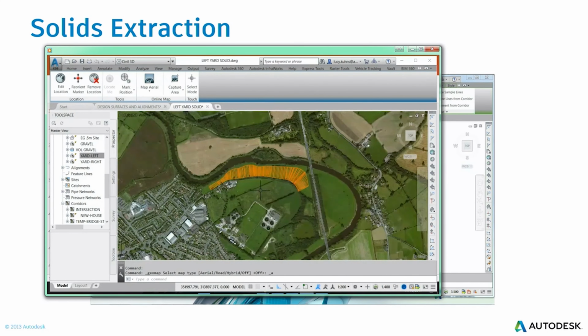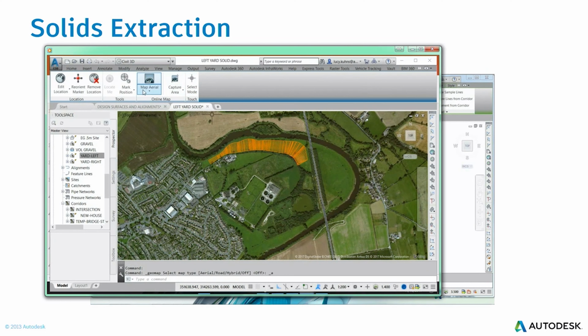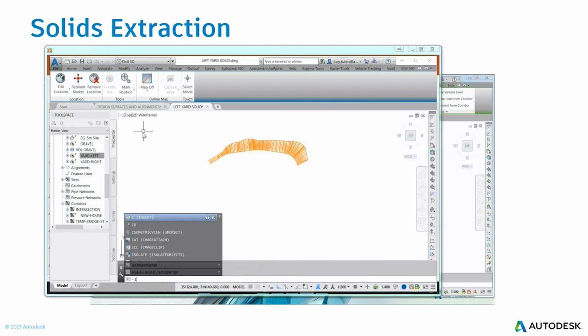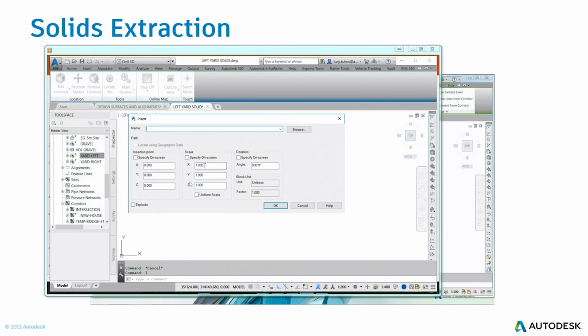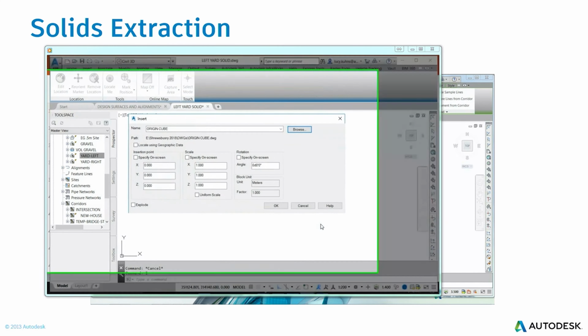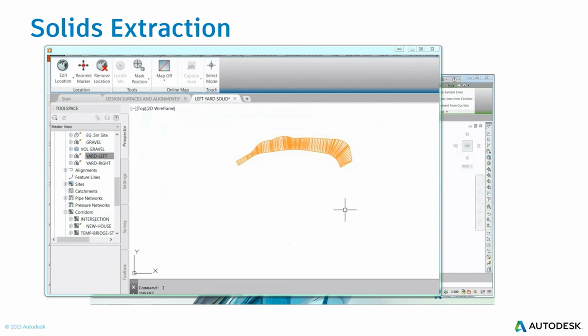And once you have that, you're setting yourself up so that the data can be used easily in InfraWorks and in Revit. So you don't have to do any moving and adjusting. Keep it at its normal coordinates, but just make sure you get that solid square inserted. And when you insert it, don't move it. Keep it at its original place. And then you're going to be guaranteed success with this.